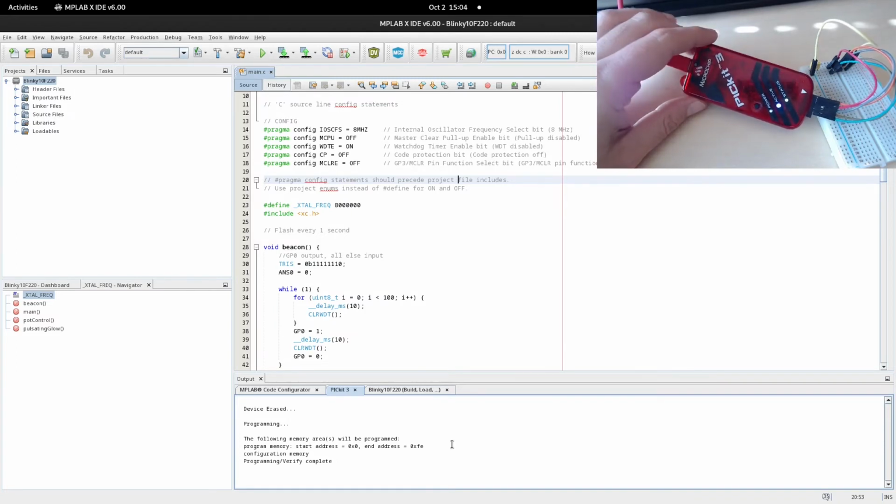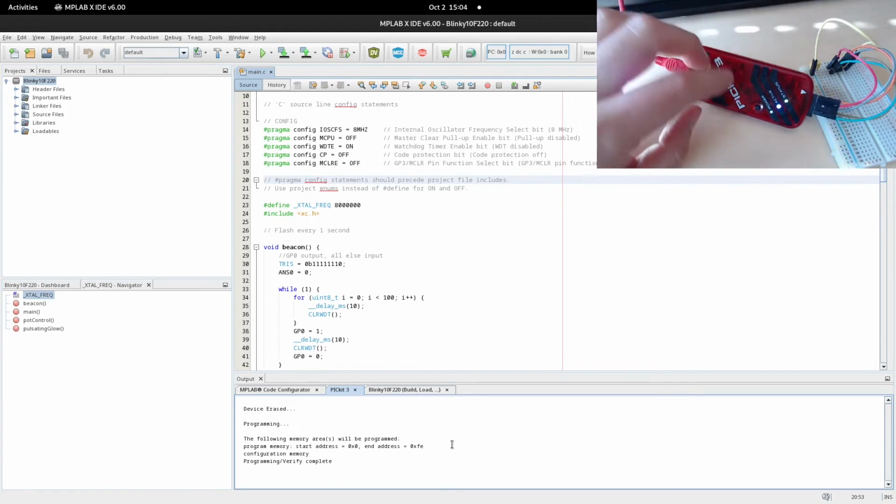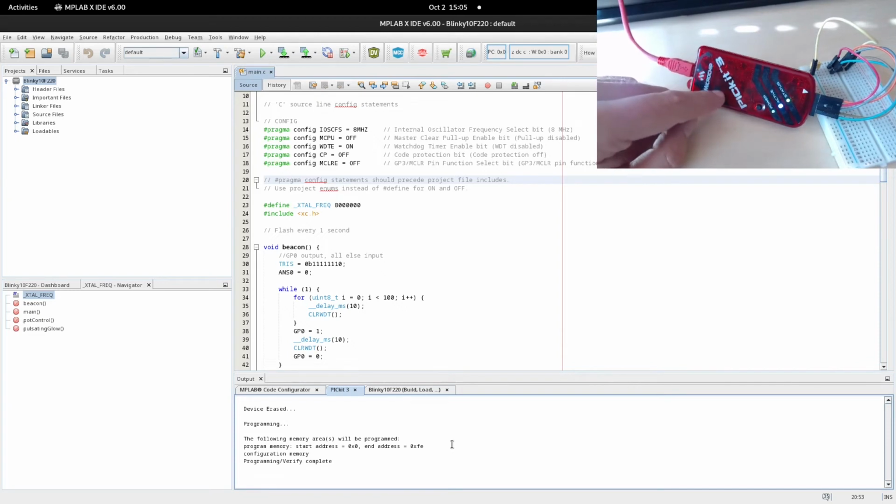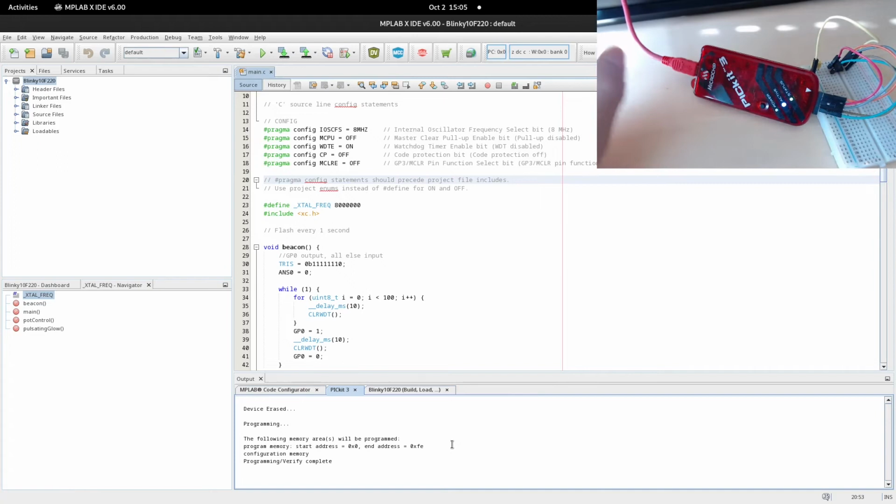They're all rubbish. They all stem from these connection issues. The state between PICKIT3 and MPLAB gets stale and then stops working. So just disconnect PICKIT3, wait for 5 seconds, pop it back on. If it doesn't work, you need to just turn off your MPLAB and turn it back on. If you're having these issues very frequently with the USB connection, then again, just don't use any hubs or peripherals.